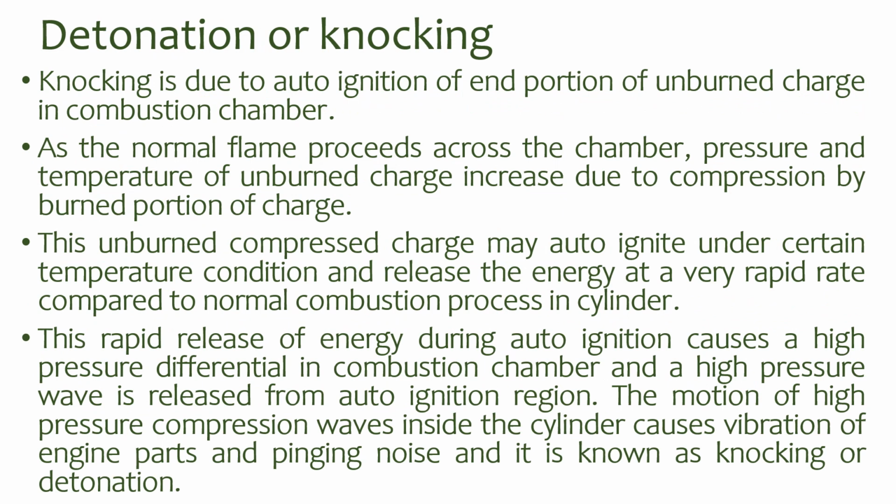Detonation or knocking. Knocking is due to auto-ignition of the end portion of the unburned charge in the combustion chamber. As a normal flame proceeds across the chamber, the pressure and temperature of the unburned charge increase due to compression by the burned portion of the charge. This unburned compressed charge may auto-ignite under certain temperature conditions and release its energy at a very rapid rate compared to the normal combustion process in the cylinder.